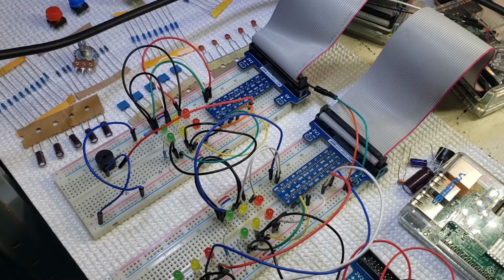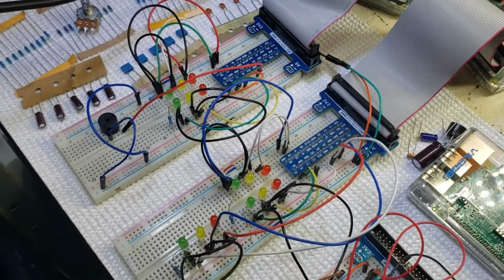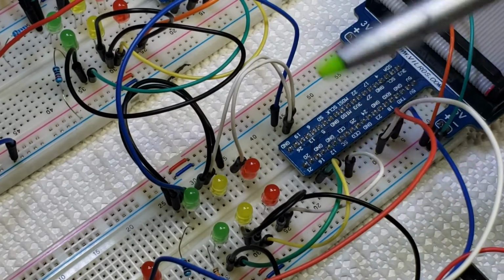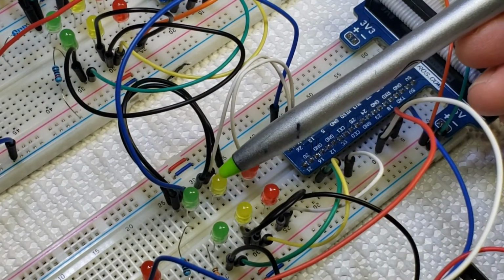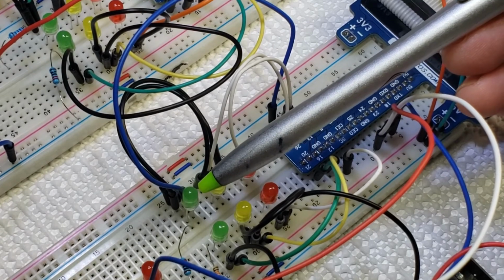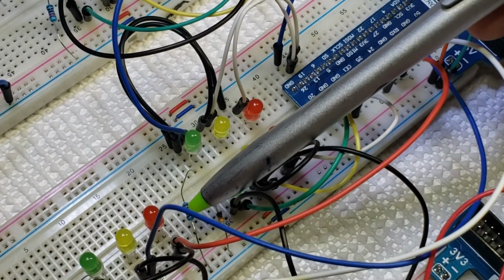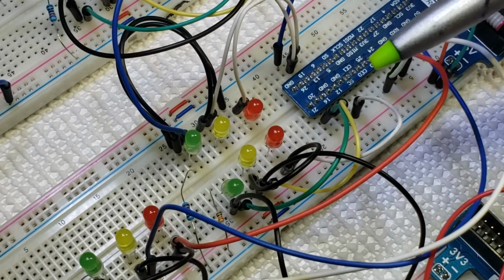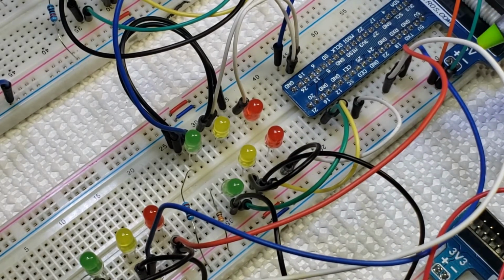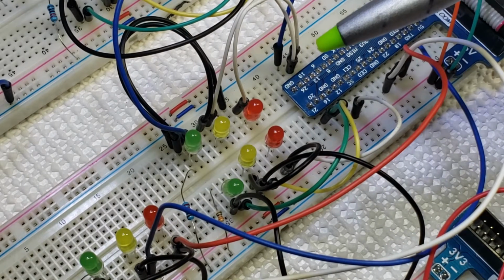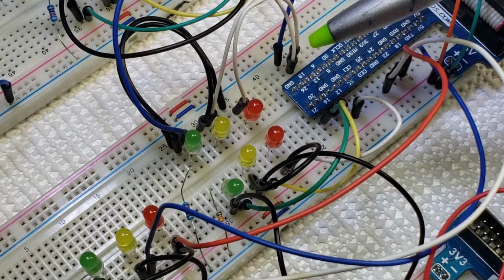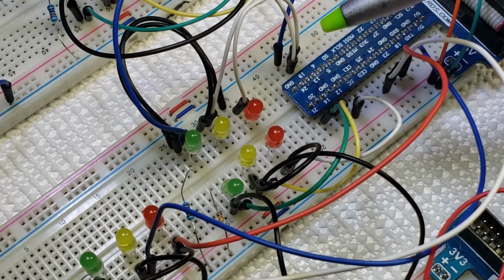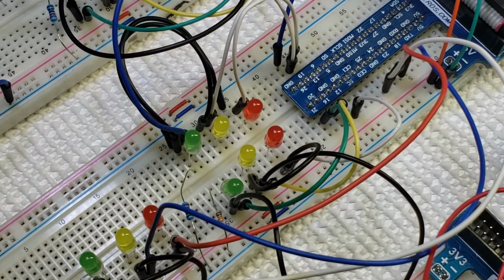For example, if we look here on the Raspberry Pi in front of us, we have a red LED, a yellow LED, and a green LED. And as you know, these LEDs have to have resistors. So what we do is we pull that resistor from our negative on that 5-volt line. And as we can see here, we have pin 13 going to red, 19 going to yellow, and 26 going to green. So our GPIO ports are all going to the positive side of our LED.